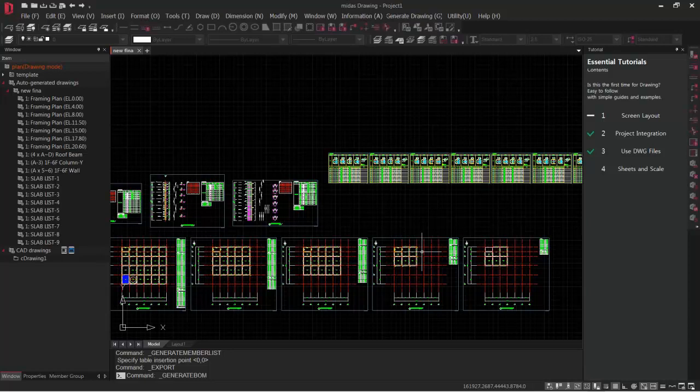Yes, there is a question about staircase. Yes, we can include the concrete or steel staircase over here. It totally depends on how we are modeling it. We can model the inclined plate elements, we can model the spiral plate elements as well, that can be used for steel or RC type of staircase, like ramps.